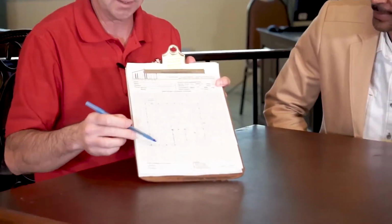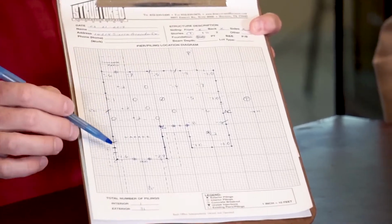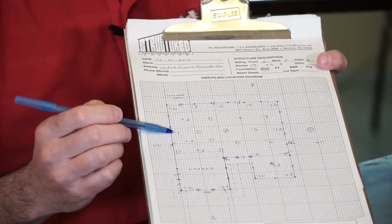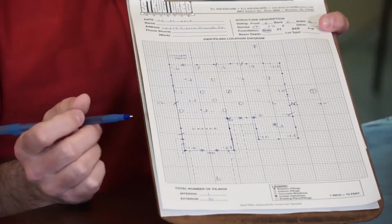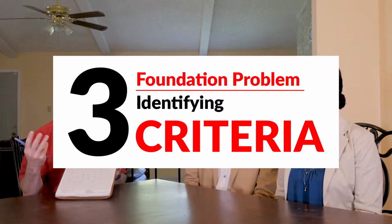Okay, so now that we've evaluated our house and we've walked around, we've drawn it up, we've marked all the stress signs on our house, we've taken a floor elevation survey. So what I do then is I take my diagram here, and my diagram is drawn to scale, and I've got all my stress signs marked where you can see these markings. This spot right here on the side is 1/10 of an inch lower than the reference spot. And so I take all of this information and I look for 3 different criteria to establish if there's a problem or not.